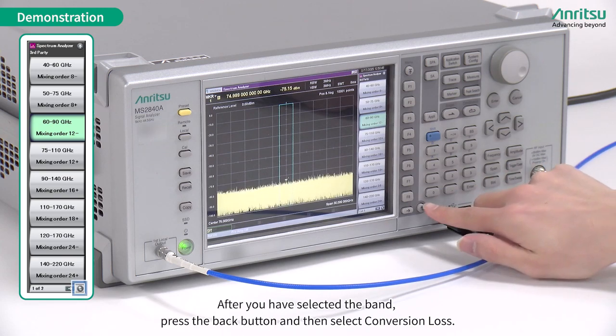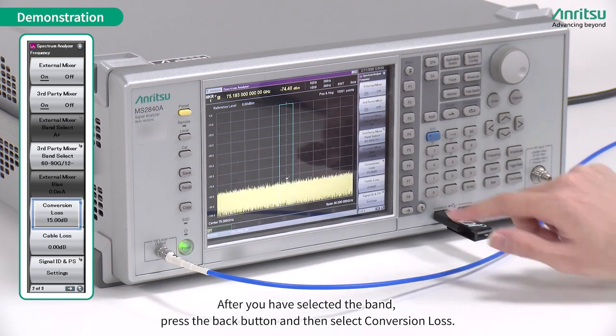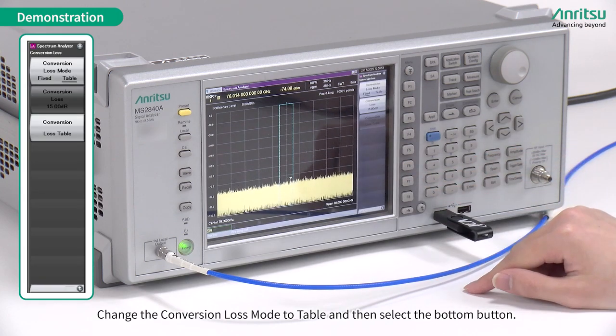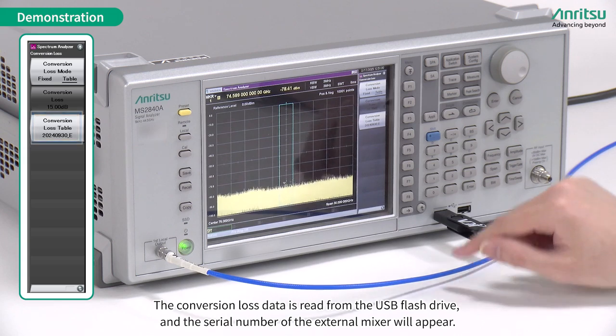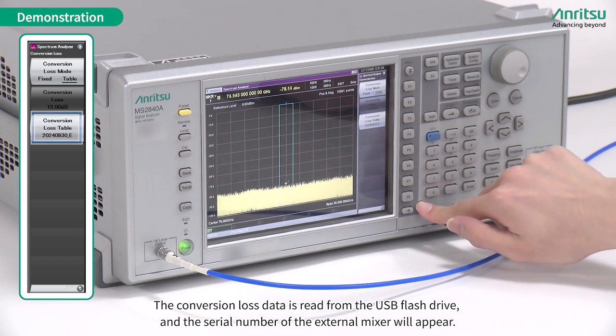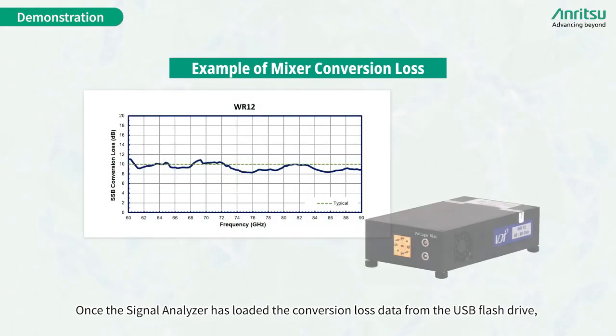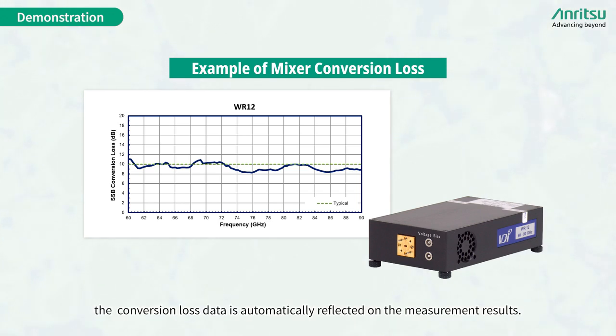After you have selected the band, press the back button and then select conversion loss. Change the conversion loss mode to table and then select the bottom button. The conversion loss data is read from the USB flash drive, and the serial number of the external mixer will appear. Once the signal analyzer has loaded the conversion loss data from the USB flash drive, the conversion loss data is automatically reflected on the measurement results.